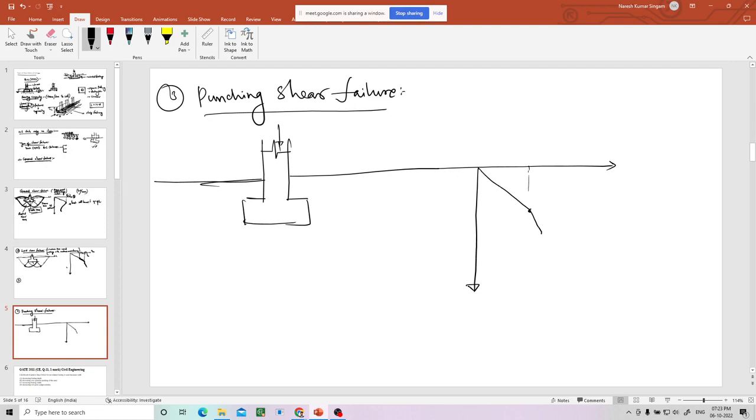Again you will observe at one particular point jerks will start here also, then after a certain point QU it will become steeper. So this is Q, this is settlement. Here it will happen in loose sands or clays with low consistency, or you can say soft clays.